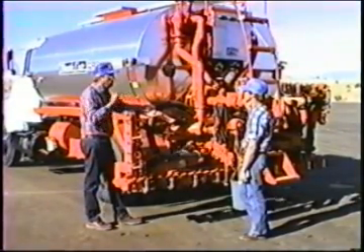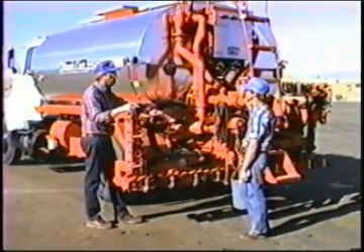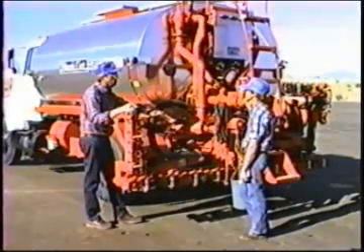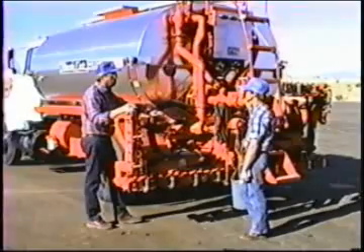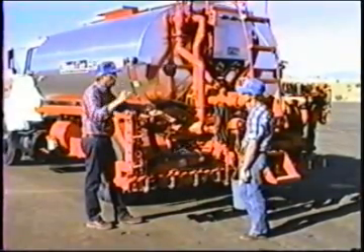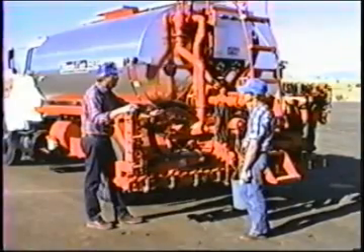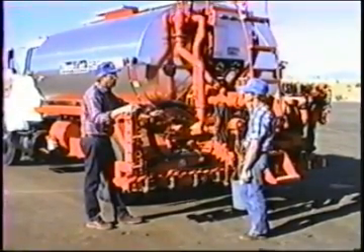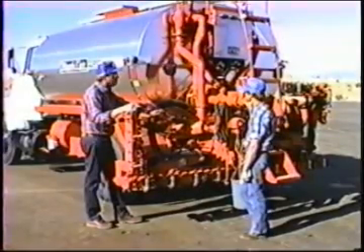That is, we have put into it 30 gallons a minute, or maybe 40 gallons a minute. That's something that you can change in the computer. That is, you can regulate the idle gallons per minute. And all that means is anytime you shut the spray bar off, the computer then tells the pump to idle at 30 or 40 gallons per minute, whatever you set into it.